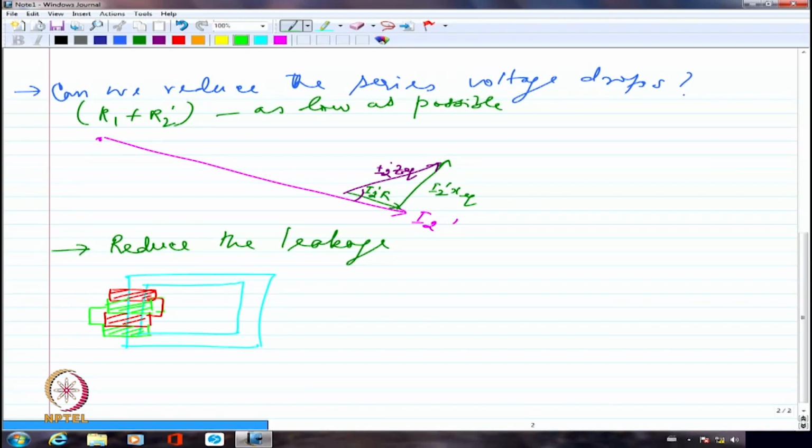I don't want the earths to be coming together. So I will have one primary 220 volts, one secondary 220 volts. From the primary I may supply the voltage, from the secondary side I may connect it to some motor or load or rectifier or whatever. So I want isolation very clearly between the primary and secondary, in which case they will be of the same voltage rating. So I can put them like this.